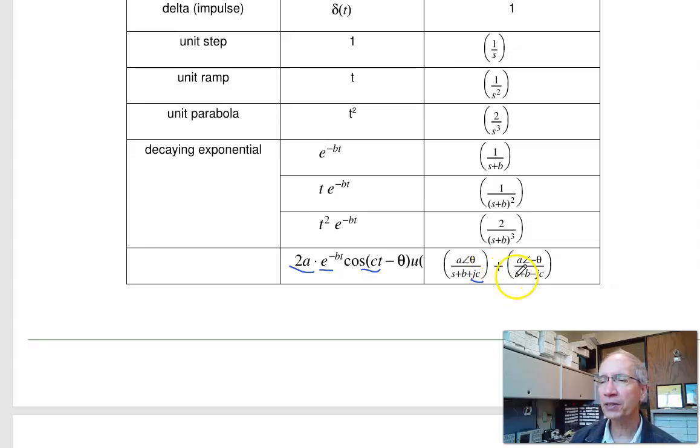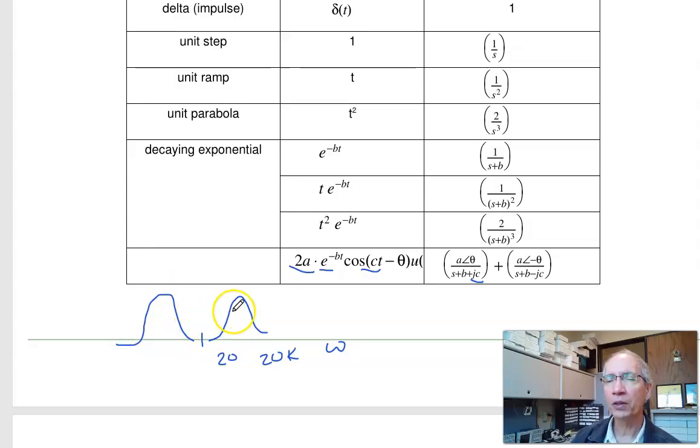And the reason you get a complex number without its complex conjugate in communication systems is this. If I take an audio signal, that's like your 20 to 20 kilohertz bandwidth. So this is frequency, there's your audio component, plus it'll have its complex conjugate. That's what audio looks like in the frequency domain. Now to do AM radio broadcasting, I'll modulate this at a megahertz. So the carrier frequency is, say, 1 megahertz. And I'll have the upper sideband and lower sideband, the complex conjugate, centered at 1 megahertz.